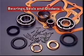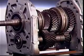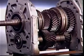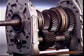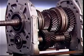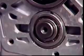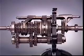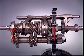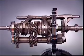This section examines bearings, seals, and gaskets. In a manual transmission, the gears and shafts are supported on bearings or bearing surfaces. This allows for rotation and also maintains the alignment of the components. The type of bearing used at each locating point depends on the load which must be sustained. Radial loads try to force the gears and shafts apart. The bearing, therefore, carries the load along its radius.